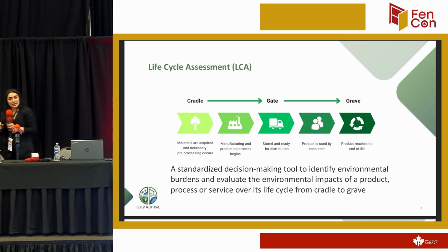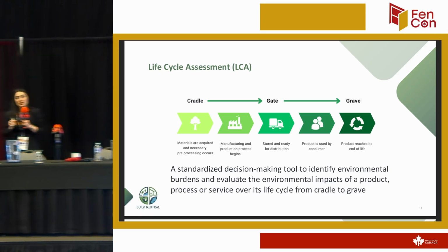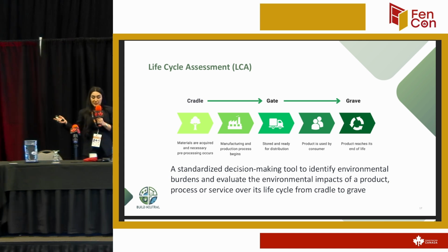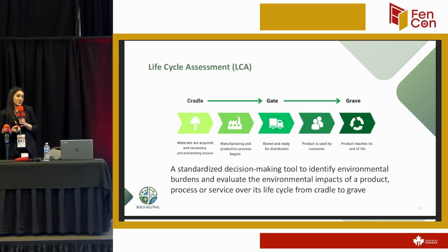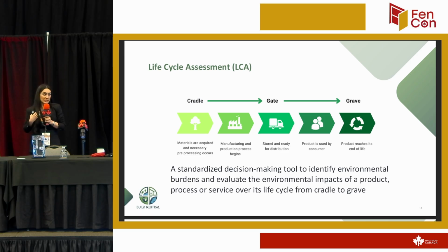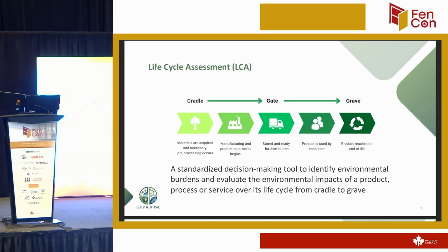Cradle to gate means that you are not considering what you are going to do when the end of life of your window comes up. If that was the case, your system boundary would be cradle to grave, which considers the use stage, the energy, and how many times you are going to replace your window over the life cycle of a building, if we are considering 60 years or 75 years, depending on the building life cycle.